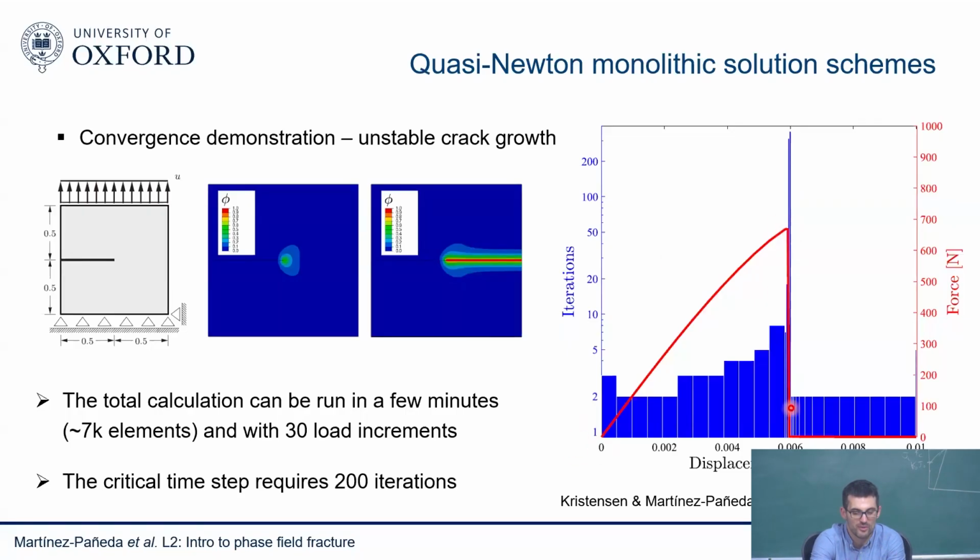So basically, you have a big jump, and this is what Newton-Raphson has an issue with, right? This is a nonlinear problem. You are somewhere here, and then Newton-Raphson needs to find the next solution, and the next solution is all the way here, and so Newton-Raphson is exploring this area and struggling. This is why it's a problem. You can see phase field has no problem.